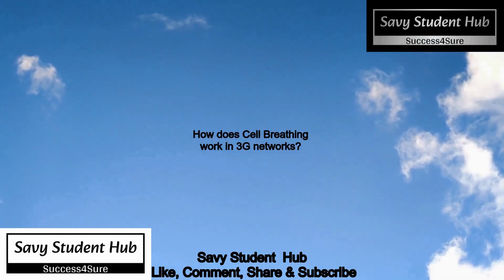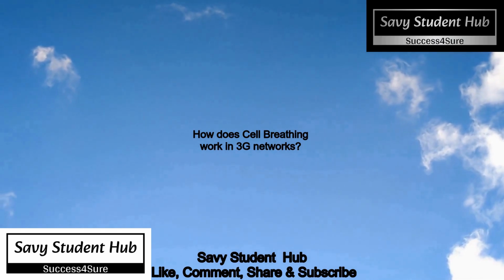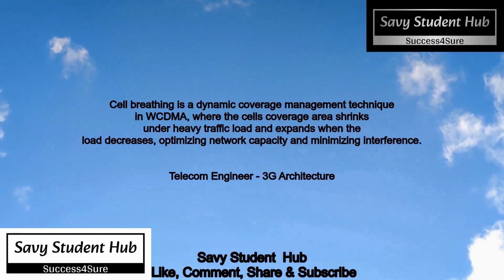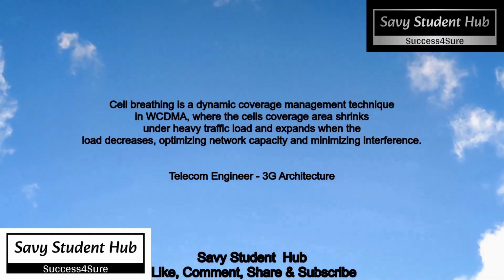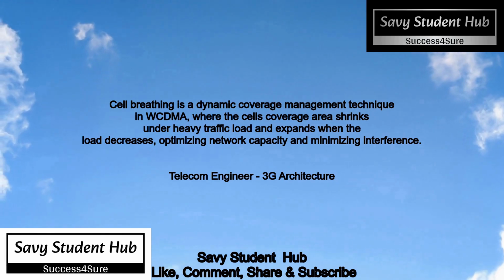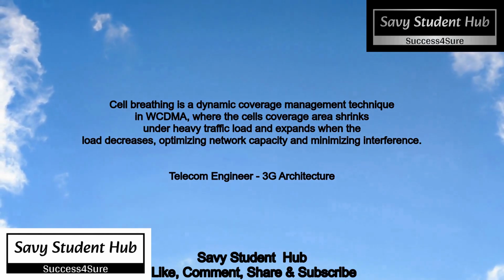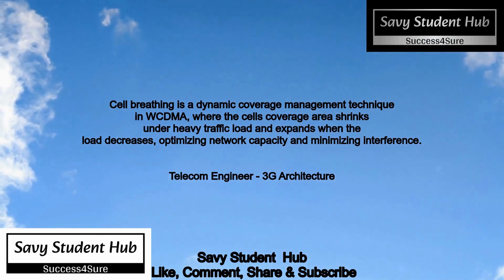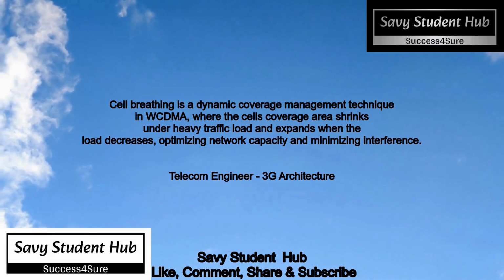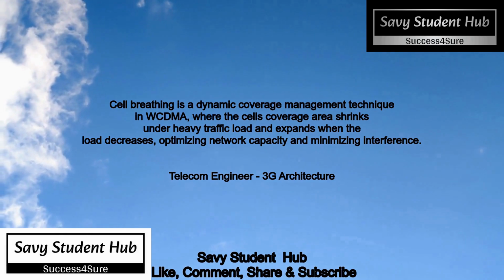How does cell breathing work in 3G networks? Cell breathing is a dynamic coverage management technique in WCDMA, where the cell's coverage area shrinks under heavy traffic load and expands when the load decreases, optimizing network capacity and minimizing interference.